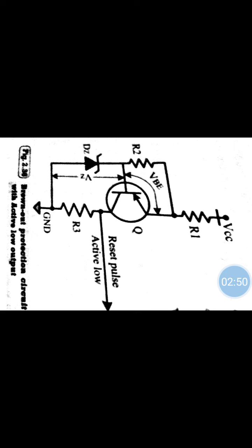So, the supply voltage to the processor starts to drop, and if this voltage falls below the threshold voltage, then the processor behavior may not be predictable. That means it may lead to data corruption. So, in order to avoid this, a brownout circuit is needed which provides protection to the processor. Look at the brownout protection circuit.